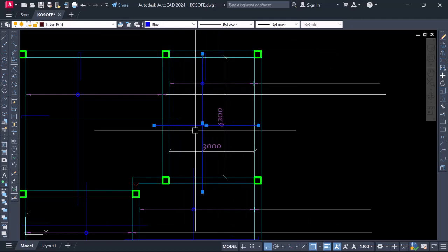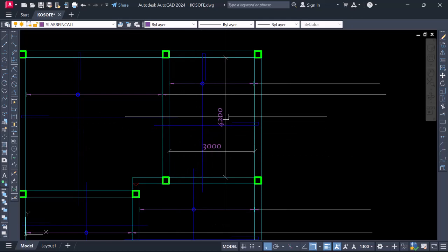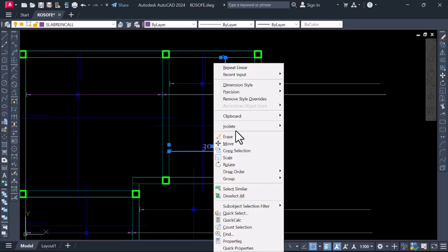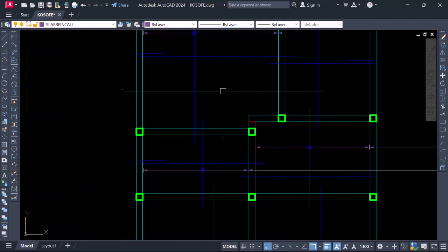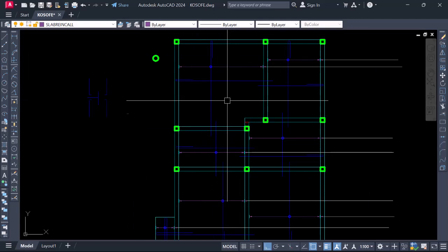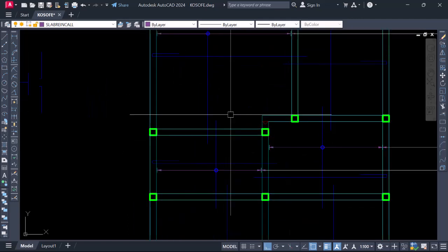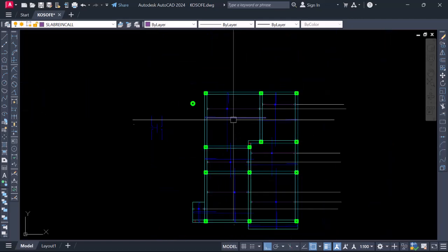Why the one running along the shorter span is the main reinforcement. All right, the one running along the shorter span is the main reinforcement. So if you got that, we're going to still apply that in the top rebar. In this area, to ease the beam moment running along this beam, it is good that we add our top bars along the side.